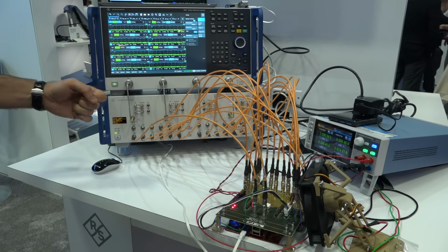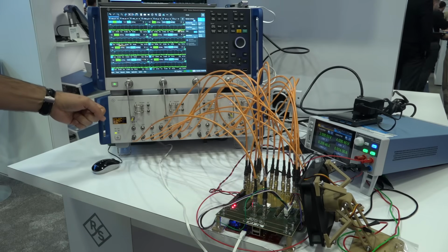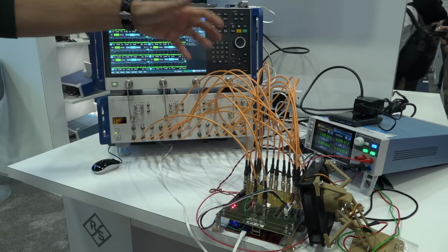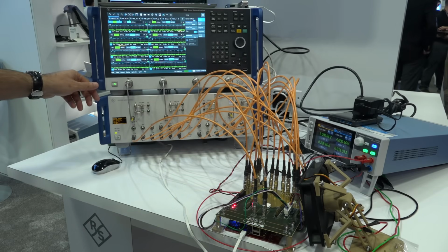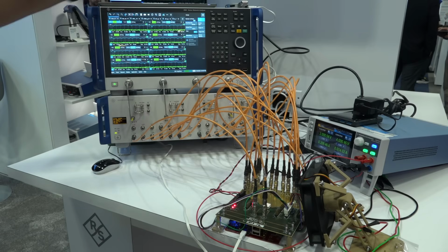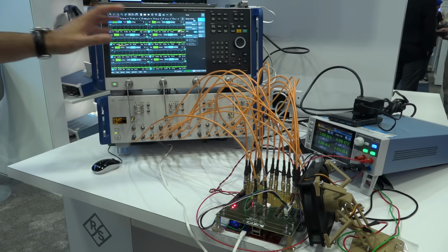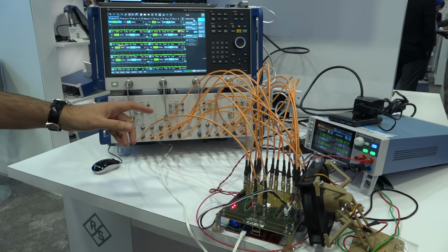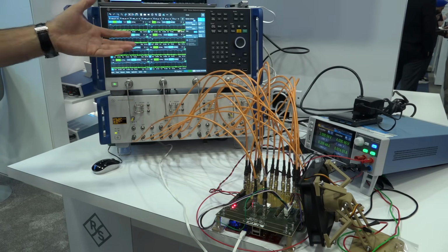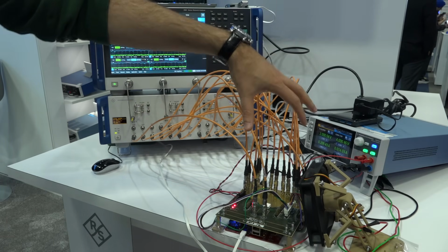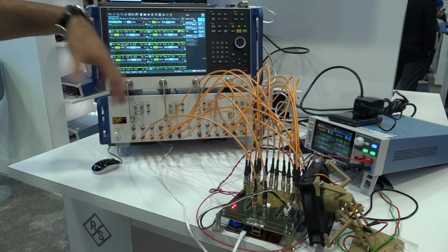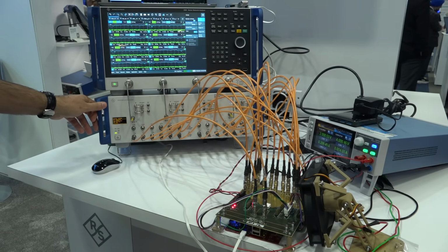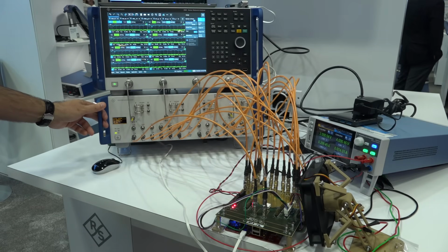But the combination of a solid state rapid switch box and a super fast network analyzer means that you can do these things that normally would take a long time extremely quickly. And obviously advanced software, compression and other capabilities of the ZNB allow you to do more sophisticated nonlinear characterizations of the transmitter and receiver. And you have complete software control, so you can also adjust the settings of your DUT while you're measuring it, basically having an automated, very rapidly running system to characterize these kinds of complex multi-port devices.